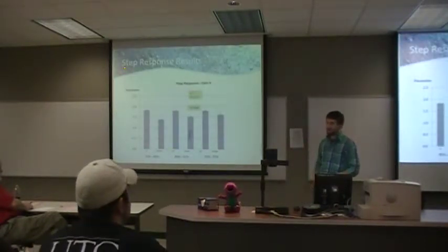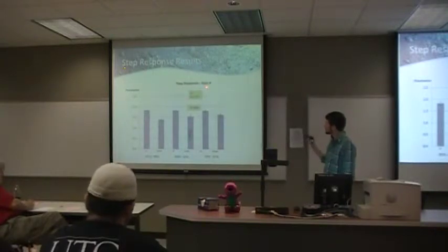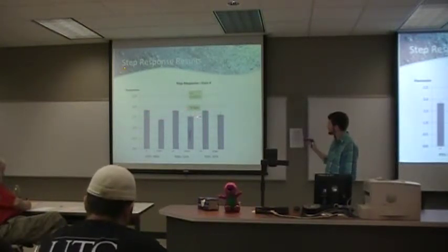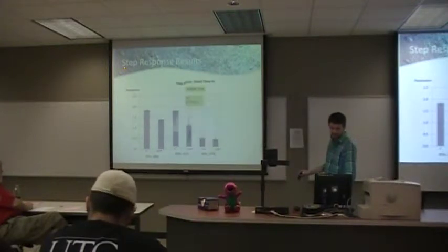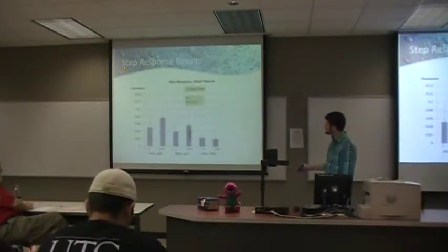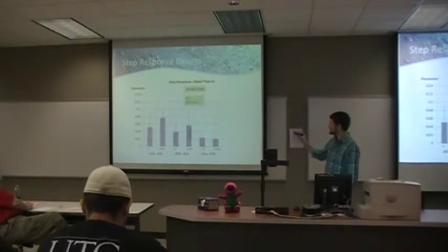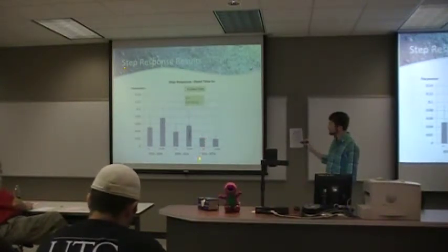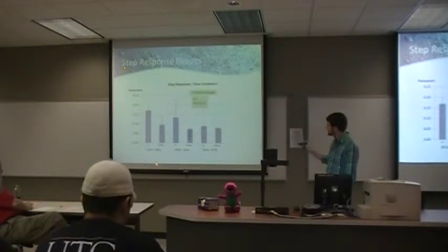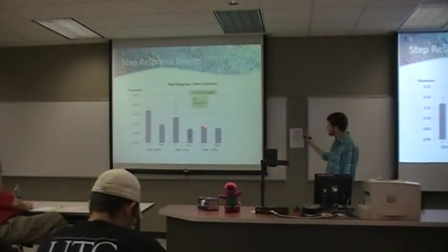We do that for all of our ranges, and we come up with our step response gain. And here you can see that the gain for the step up is approximately the same, step down is approximately the same. It's a different story for the dead time and time constant. When you look at the up and the down, you can see it almost looks like you could draw a straight line. In fact, it would be very interesting to compare the rest of this data to what the red team has, so that we can see if it had a trend of falling. It's the same for the time constant. You can see, for example, the up falls down.